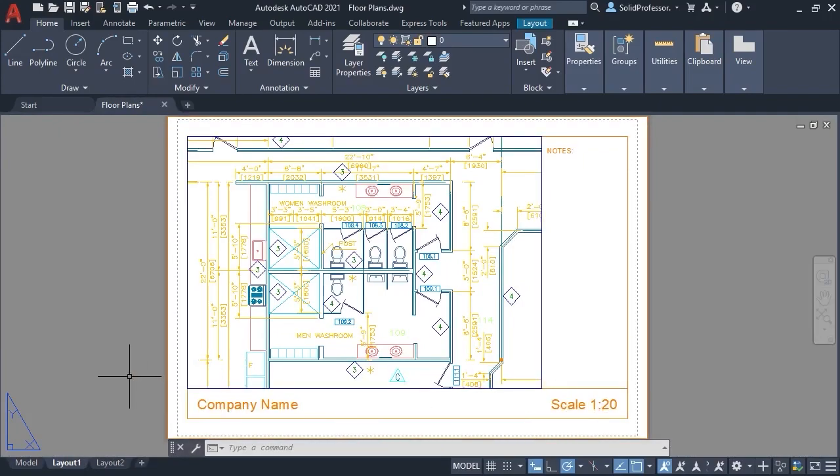The viewport itself is simply a window into the model space, meaning that any updates made there will be displayed here as well. This setup also means that you can create as many Layout tabs as you want, focusing on any number of different elements without having to worry about updating them. The Layout tabs can then be easily printed and plotted for collaborative work. Taking advantage of this structure allows you to spend more time designing and less time updating.